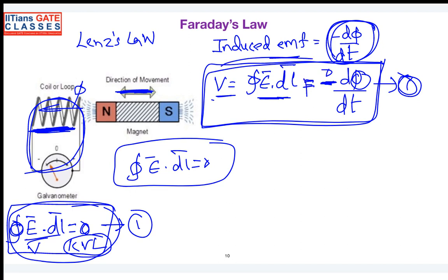Now in this case, it is not equal to 0, which means there is something still there. The source is producing something, the load is absorbing, but there is some other term, which is nothing but a voltage that is not produced by the source. That is what I was saying. It's a non-conservative field. That is the reason why your KVL is not applicable. If KVL is satisfied, the electric field should be conservative, and then straight away you can say E dot dl is equal to 0.